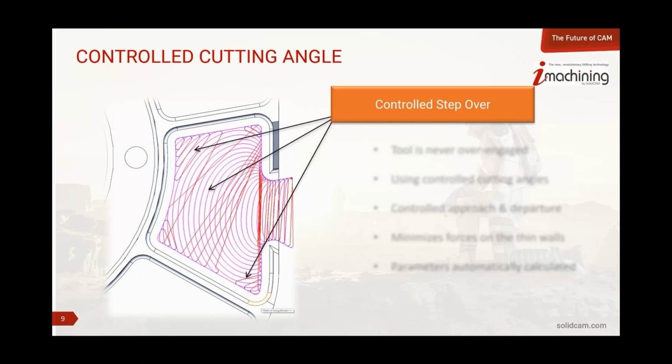Now, step over on one size tool is completely different from the same step over on another size tool. You take a 1/4-inch tool with a 45-degree step over or 45-degree cutting angle. That radial step over is going to be completely different than if you're on a 1/2-inch tool with a 45-degree cutting angle. So one of the things that we do is we ensure that the tool is never over engaged. We're going to make sure as we're working through this spiral, the morphing spiral, that we never over engage that tool. It's always safe. It's always protected. We're going to control those cutting angles.